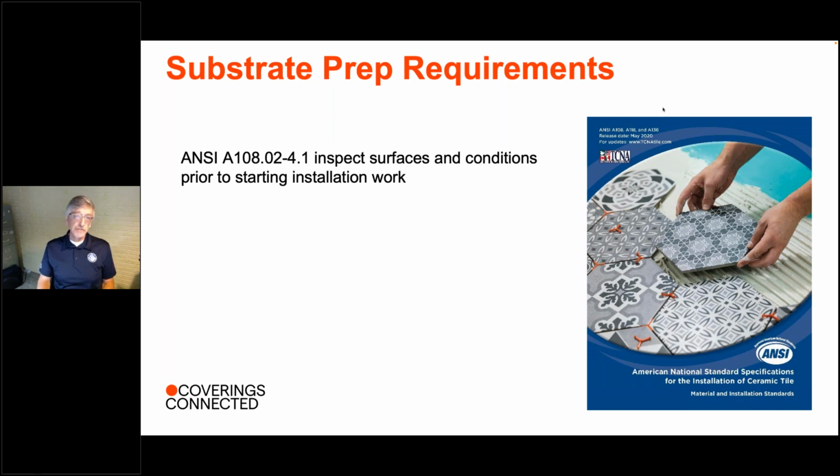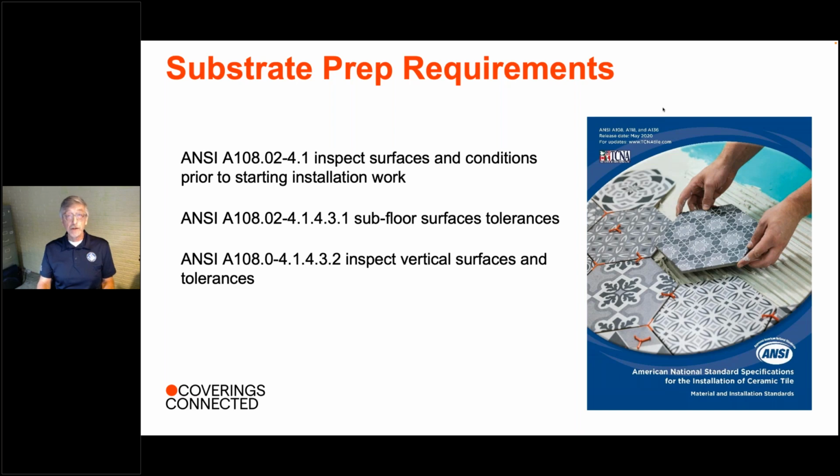We need to understand as tile industry professionals, and by professionals, I mean specifiers, architects, designers, contractors, installers, estimators, project managers, distributors, salespeople, all manner of tile industry professionals need to understand the requirements for substrate flatness that is found in ANSI A108, and to make sure that requirements to prepare that substrate are contained in every specification, that somebody is getting paid to make that substrate flat for our finished tile installation. Critically important. And here's where we find that information.